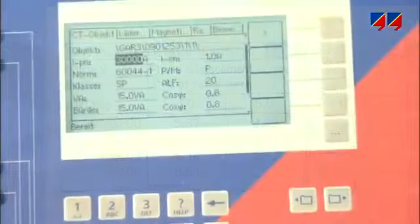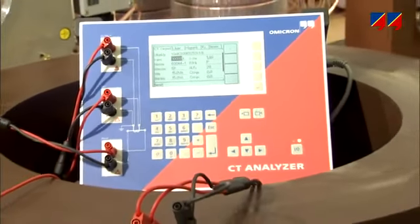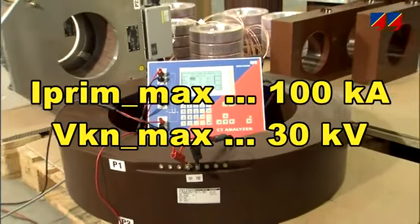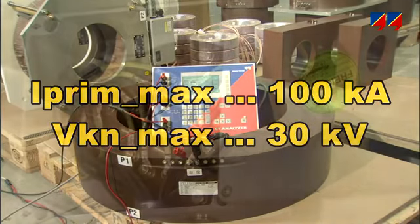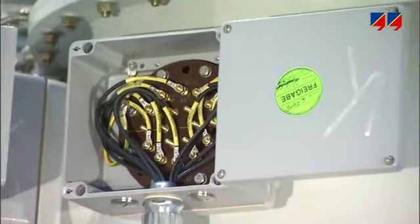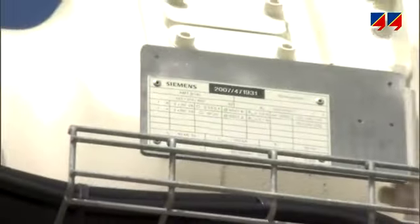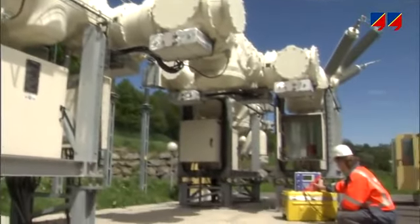Using this approach, all types and sizes of CTs can be tested, even exceptional types with primary currents of up to 100 kiloamps or with knee point voltages of up to 30 kV. It can test any CT, including installations that by conventional methods have been difficult or impossible to test so far, such as CTs in transformer bushings or gas-insulated switchgear.